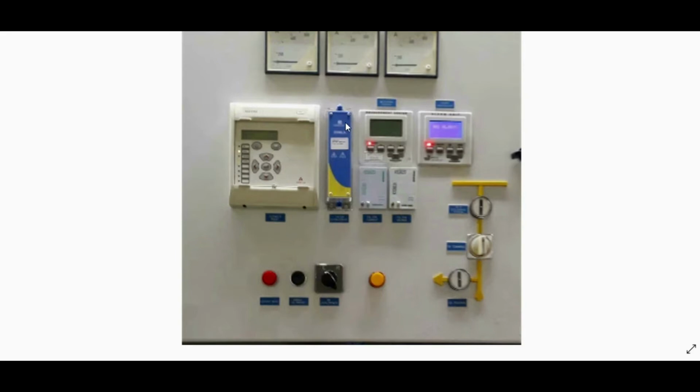Current, voltage, binary inputs and DC power supply first come to the test block and then they go to the protection relay, and binary outputs from the protection relay go to the test block, and from the test block go to the other part of the circuit. Okay, let me add something else. It's not necessary for all binary outputs and binary inputs to be transmitted through the test block, because the commissioner needs just some of them, not all of them, for the testing of the protection relay.